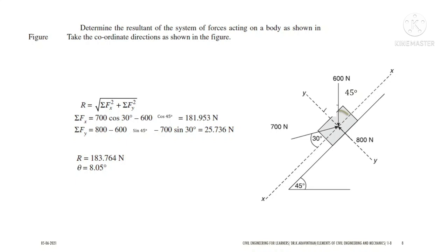Okay, let us come to this problem here. Like that, in this problem you can see many things, but after understanding the concept of a coplanar concurrent force system, to get the solution of this type of problem you need resolution of forces. First, you can see that this is a coplanar force system. Why? Because all the forces are acting in a single plane and the forces are concurrent at a single object. Now you have identified it as a coplanar concurrent force system.